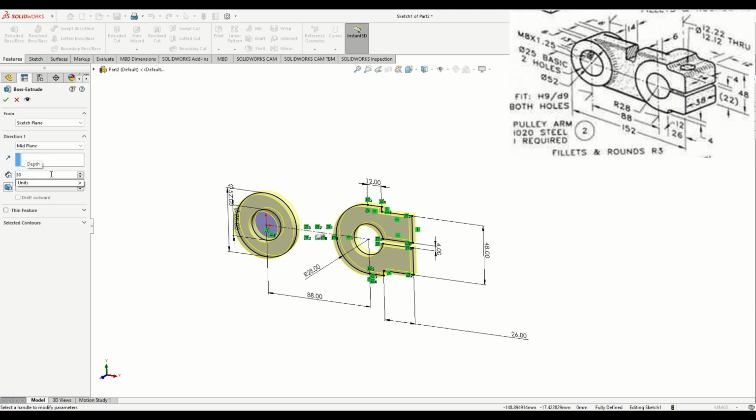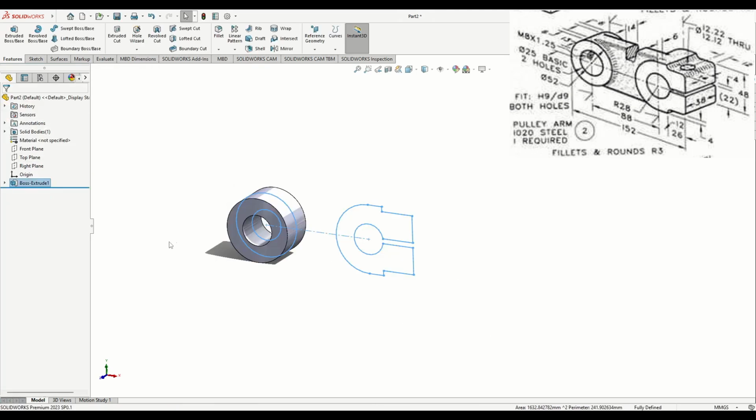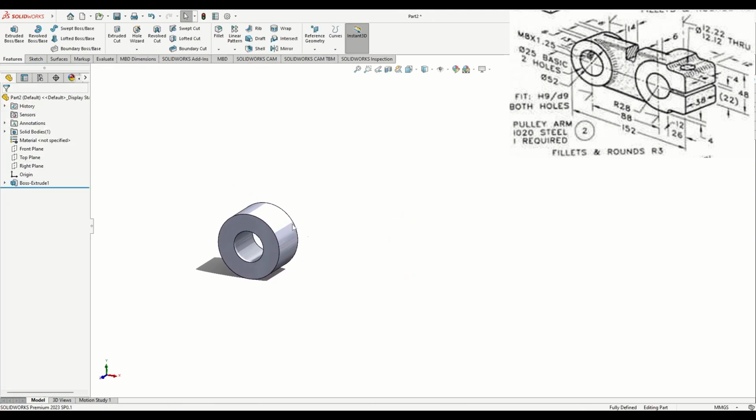I know you cannot find it on the drawing, but if you have the drawing right now and you are looking at it, it's 6 on these two sides and then it's 14 for that kind of rib in the middle. Not in the middle actually. Okay, and we'll use here 30 millimeters and then we'll go down here to select the contours. We don't want both of these, we only want this one. So select this one and press OK. Perfect, and now we have one cylinder.